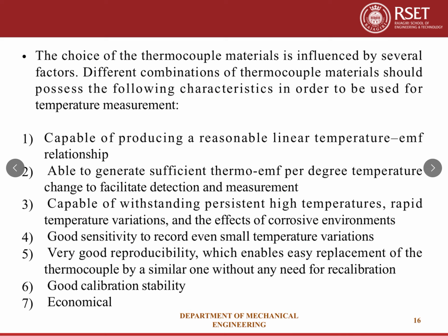The choice of thermocouple material is influenced by several factors. Different combinations of thermocouple material should possess the following characteristics in order to be used for temperature measurement. Capable of producing a reasonably linear temperature-EMF relationship. Able to generate sufficient thermo EMF per degree temperature change to facilitate detection and measurement.